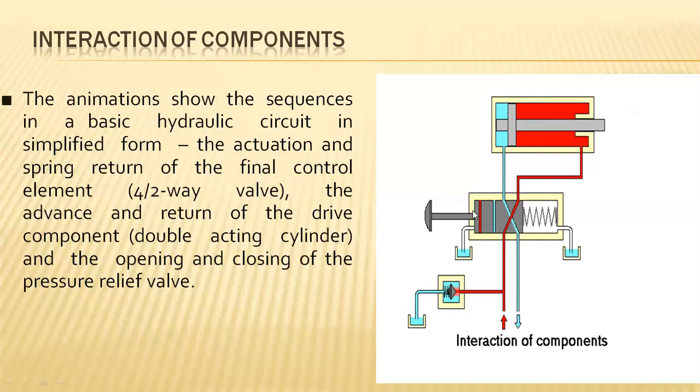And hence straight connections, when you have pushed this button, these two connections will be coming into these positions. It will be entering in a forward direction, and the return fluid will be drained back to the oil reservoir. That is the first condition. And at the initial stage, already entered fluid will be drained to this oil reservoir back again.